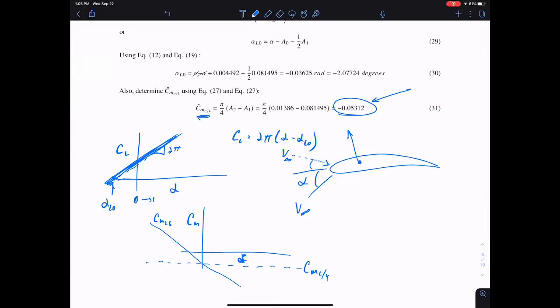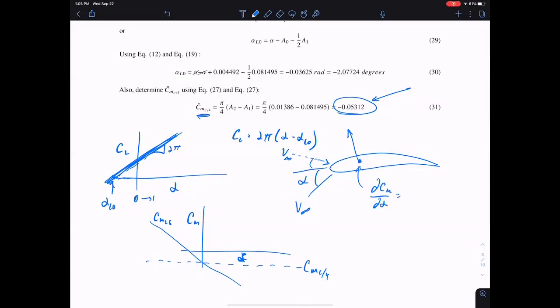Okay, Trevor, you got it exactly. It's because it is the aerodynamic center as predicted by thin airfoil theory. Thin airfoil theory says that there's a special location at the quarter chord where the change in pitching moment with respect to alpha is zero. That's the definition of the aerodynamic center. Now we're going to define that not only for an airfoil, but for an entire airplane, and we'll talk about that. This definition holds more broadly than just thin airfoil theory. It's just a definition for the location of the aerodynamic center: this special place on this object where the pitching moment doesn't change if we change angle of attack. But thin airfoil theory says that happens exactly at the quarter chord. So if you compute the pitching moment about the quarter chord, that is going to be independent of angle of attack. And that's what we see here. That's what this number is right there. Okay.